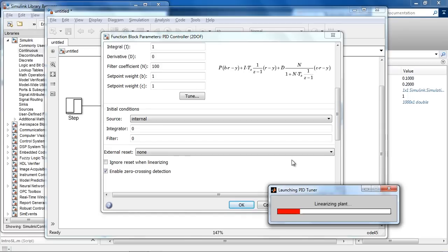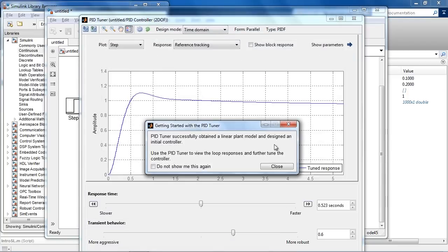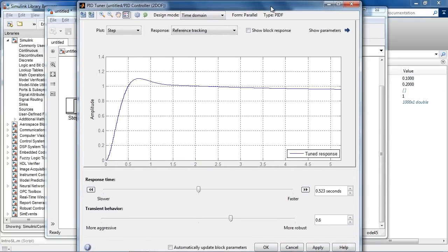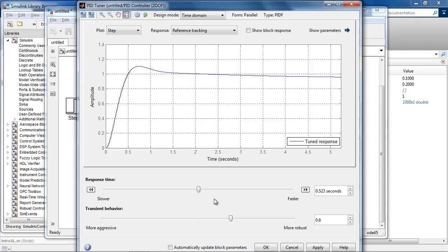And you know what I like about what you just did? You just switched to discrete time, and now you're going to have a hybrid subsystem, a hybrid model in Simulink. And all you had to do was click that discrete time button in order to get that. So, that's pretty powerful stuff. You've got your discrete time controller and your continuous time plant model, and you didn't have to do a lot to get that to work.